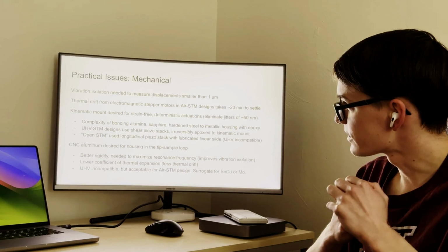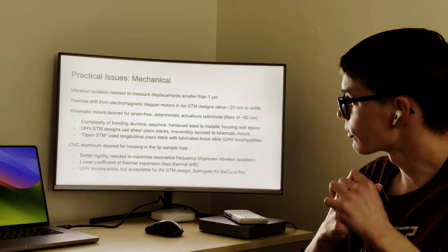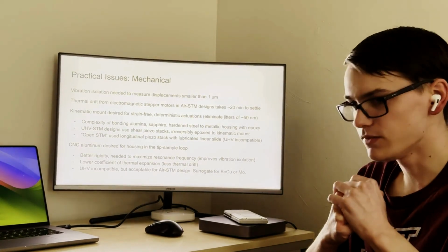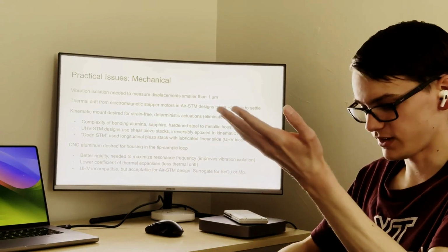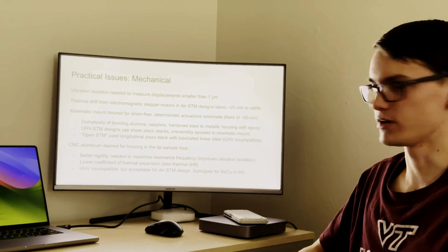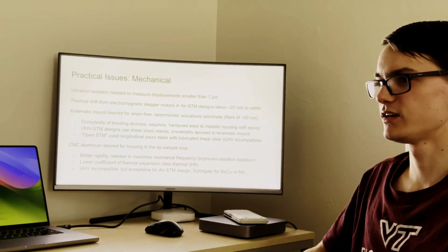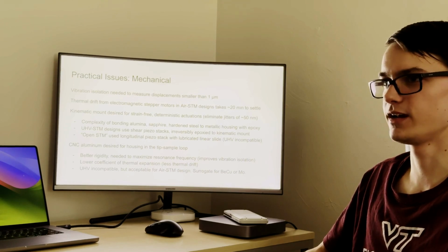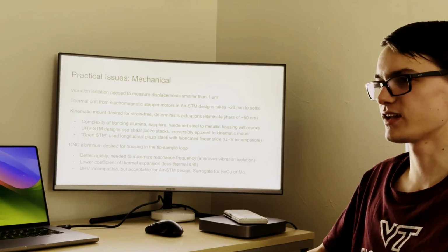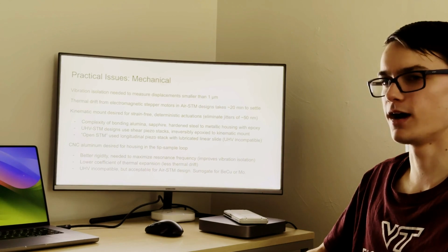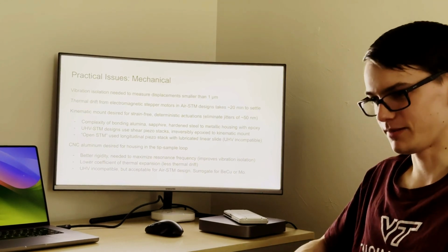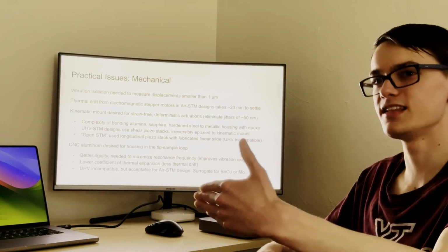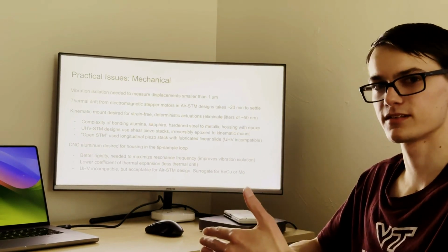I haven't seen anything except kinematic mounts be used, or extremely flat and weird tolerances for the legs of stuff that has hundreds of nanometers of range. You can have some other weird designs. I looked all the way at the beginning of STM, Binnig and Rohrer and some of the other early STM designs, and they had some really weird walkers. Sort of like that redstone contraption in Minecraft that picks up its leg and walks. It's exactly the same concept, but with piezos.